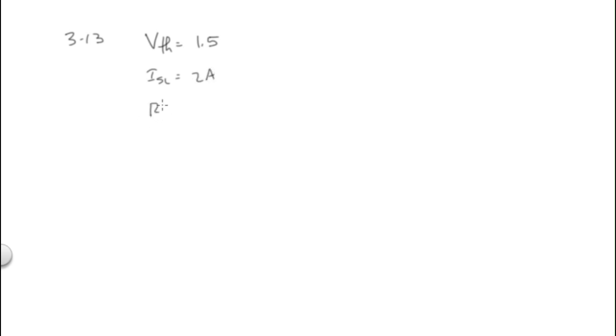R Thevenin, well, V equals IR, so 1.5 is equal to 2 times R Thevenin, or R Thevenin is equal to 1.5 divided by 2, or equal 0.75 ohms.